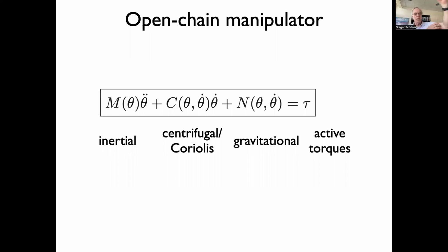If you don't have a prismatic joint, or what's it called, I forgot the English word for these segments, which you could make longer or shorter, you also write that as a transformation, but it's just constant. It just shifts along the length of the segment, and so on. You go down the chain, and then one can figure out in terms of these formulations what general kinetic energy terms and potential energy terms look like, and then you can derive these equations.